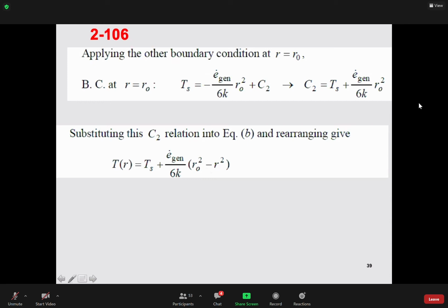Look at the difference from when you're using finite difference. Here, you can change the R at any point from 0 to 1 millimeter, 2 millimeter, 5 millimeter, and so on, and calculate the temperature at any point within the sphere. But when we are using numerical methods, since you have to slice it and discretize it, you find the temperature at a certain point. But this expression gives you the temperature at any point from 0 to the radius of the block. That's the difference between solving the differential equation and using numerical methods. But as mentioned, we can do this because this problem is well defined.